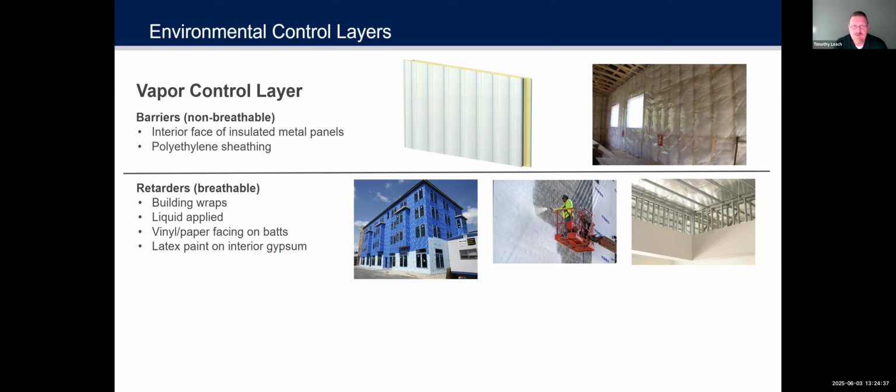These building wraps, yes, you're really going to have to stop and maybe even start over if, like in that situation, the whole undersurface gets saturated. The liquid applied, of course, obviously you're going to need a good weather day to be able to do that on the outside of a building. You certainly couldn't do that on a rainy day. So a lot of this other material can be delayed on a job site because you have to worry about weather, where insulated panels are one of those types of materials that's really not as weather limited. That's a good thing to point out.